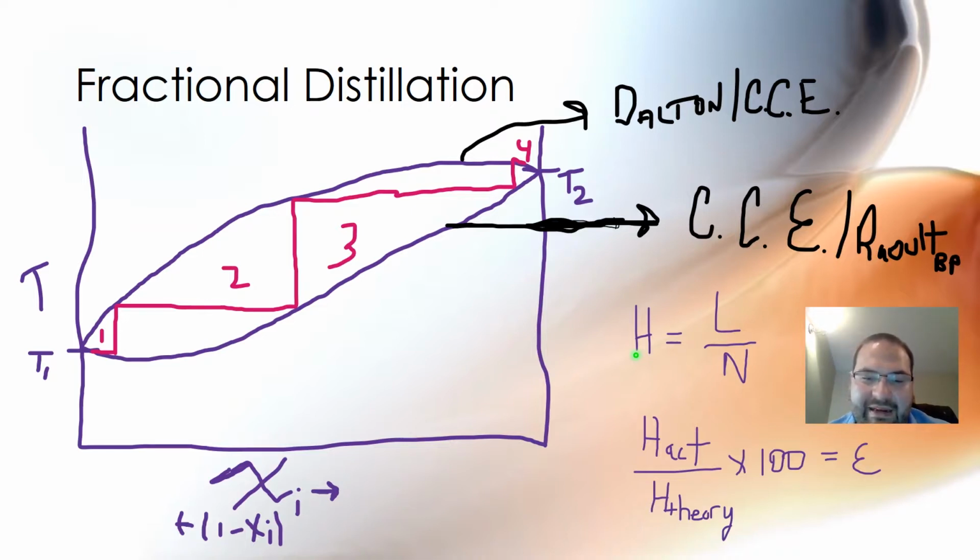More than likely, you'll have a number about 10 to 20% greater or less than the theoretical calculation of the plate height. And you'd have to take some experimental parameters to actually see what kind of plate efficiency you were getting.